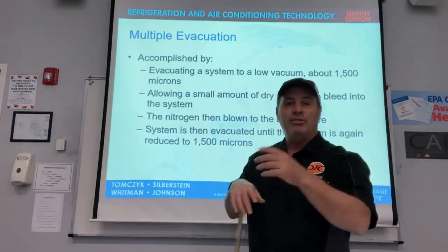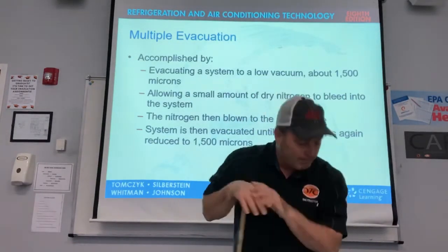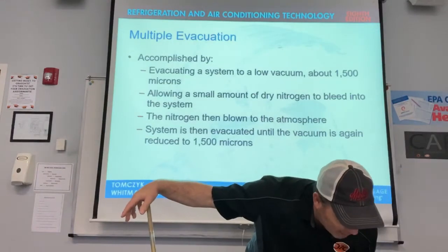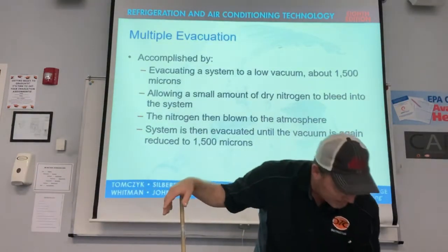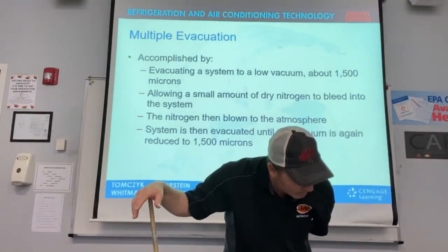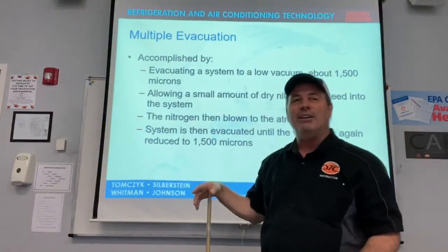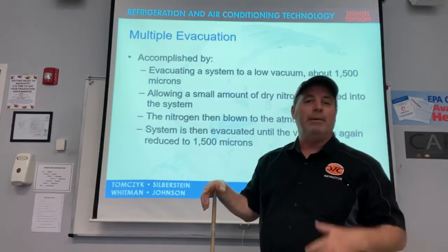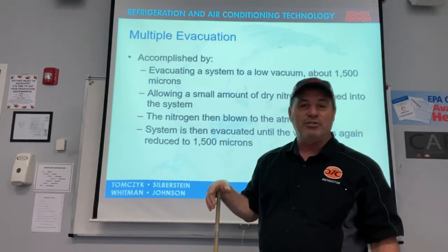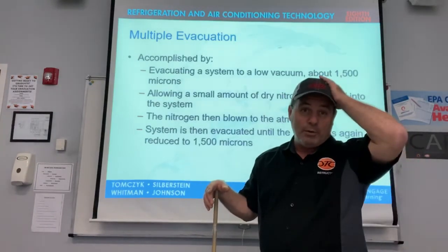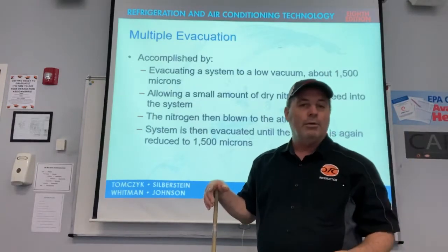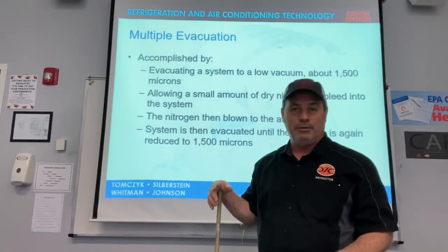And remember this, we do sublimation on page 210. The process of turning a vapor without passing into a liquid is called sublimation. So anytime you have ice in your system and it turns straight into a gas, that's sublimation. That happens from pulling a quick vacuum. But we have moisture in the system.